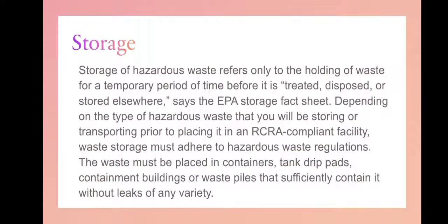So, let's proceed to storage. What is storage, guys? Storage of hazardous waste refers only to the holding of waste for a temporary period of time before it is treated, disposed, or stored elsewhere, says the EPA storage fact sheet. After you segregate the waste, you will put it in storage like containers or tanks. A trash can may work before you dispose of it, depending on the type of hazardous waste that you will be storing or transporting prior to placing it in a RCRA compliant facility.